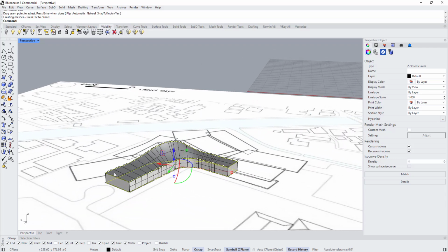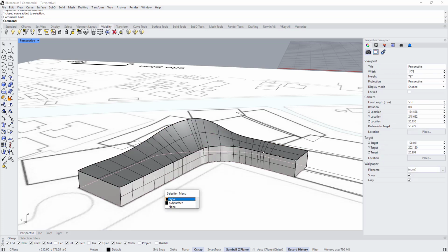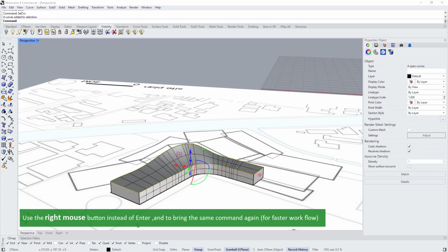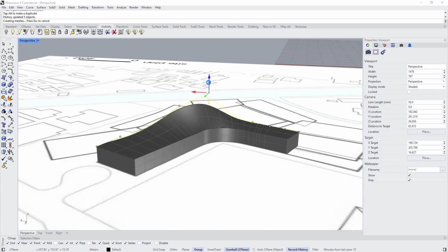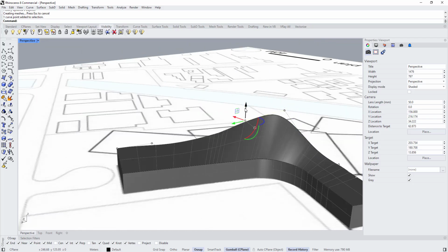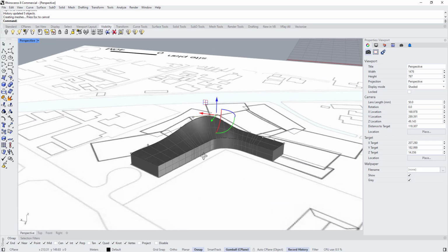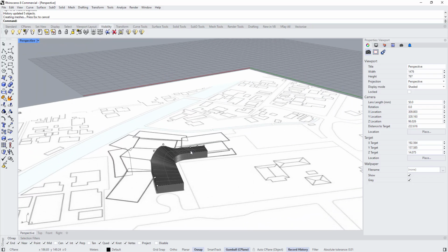So now we have our walls, and now I'm going to lock this curve and select the closed curve in the base and lock it too. So now all the curves that I want to edit to modify our design are only these 4 curves. So whatever I do to this curve, all these walls are going to be adjusted. So I'm going to repeat these processes for all the remaining curves.